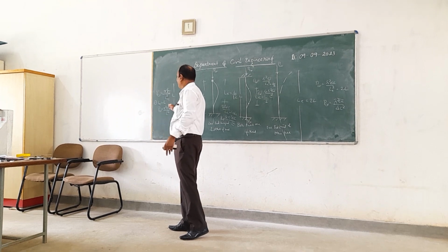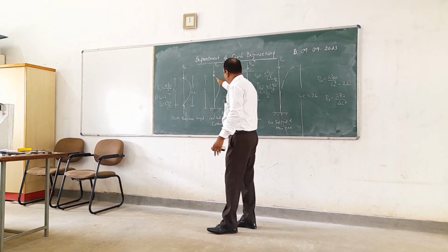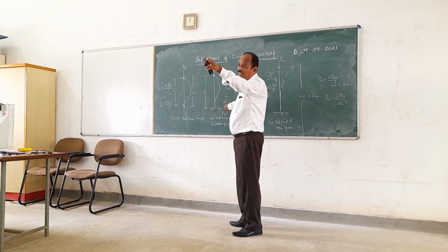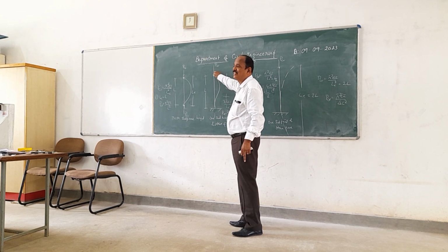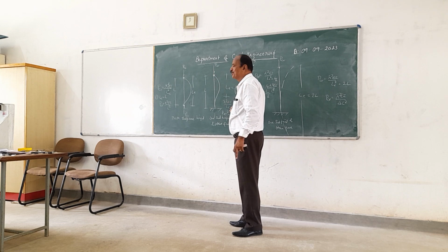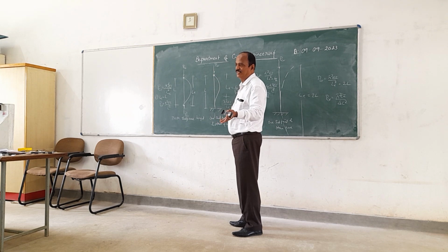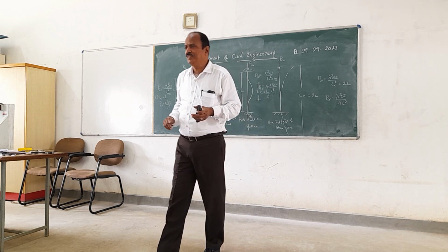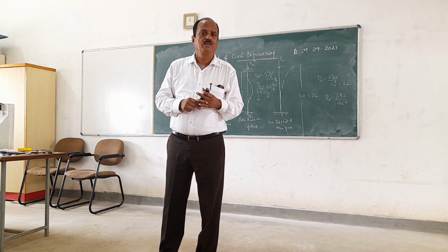If you substitute L as the effective length, we are going to get the actual load carrying capacity of that particular column when one end is fixed and the other end is hinged. The same expression comes. Right? Is it clear? Okay. Now with this as the basics, we write.